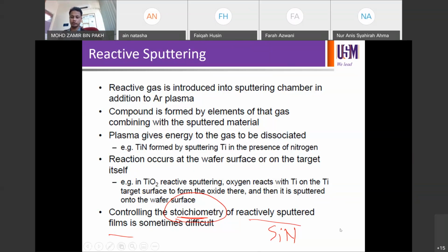Ratio of, okay, Hazika, ratio of, right? If you say silicon nitride, then ratio of what? Yes, good. Silicon and nitrogen. You want to form silicon nitride with a certain ratio. So for example, if you want to have 50-50, you can write it down as SiXNY, right? 0.5, 0.5, or 0.3, 0.7, 0.8, 0.2. So that is the stoichiometry. So if I say I want a stoichiometric deposition, usually I'm referring to 50-50 or 0.5, 0.5.